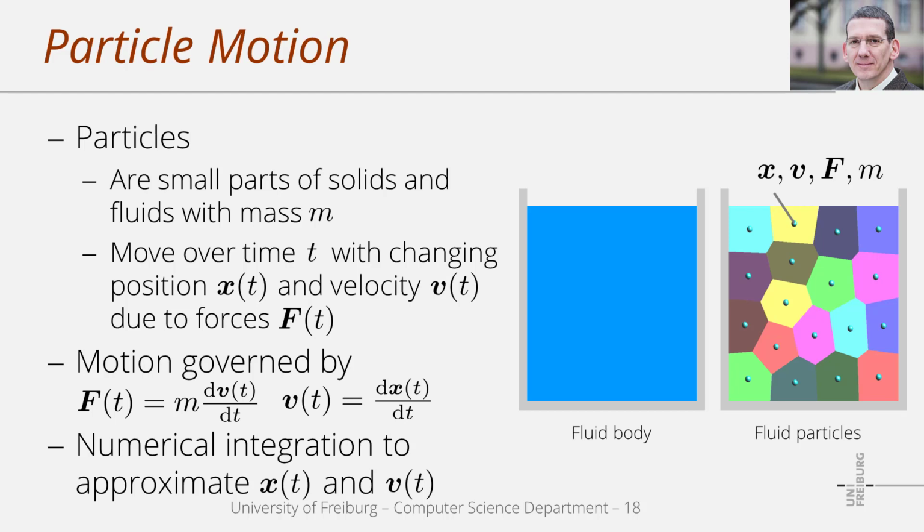In order to do so, we consider two governing differential equations for the particle motion, one for the velocity and one for the position. So the first equation states that the force acting at a particle corresponds to the time rate of change of the linear momentum, which is mass times velocity. And the second equation states that the velocity is equal to the time rate of change of the position.